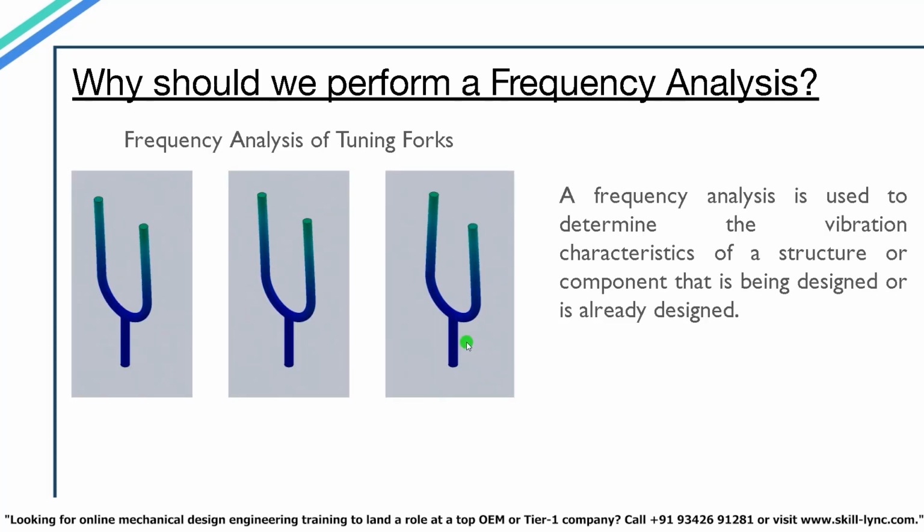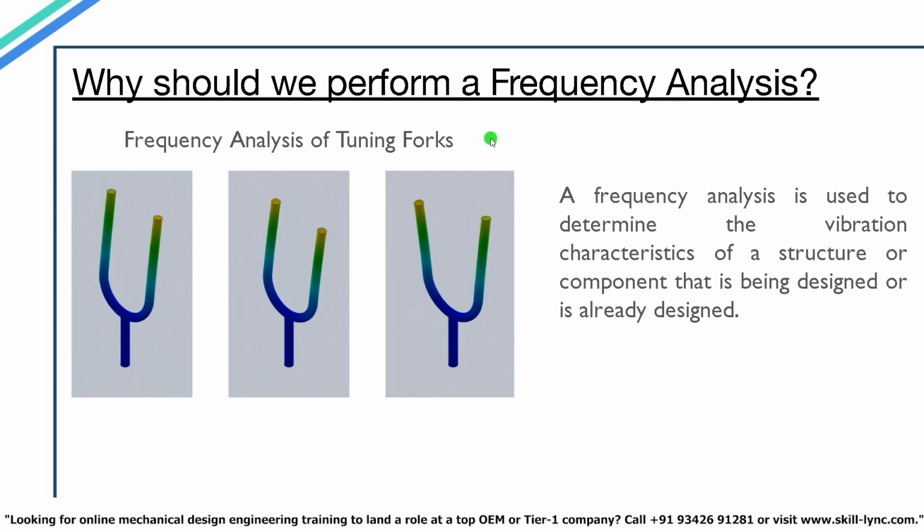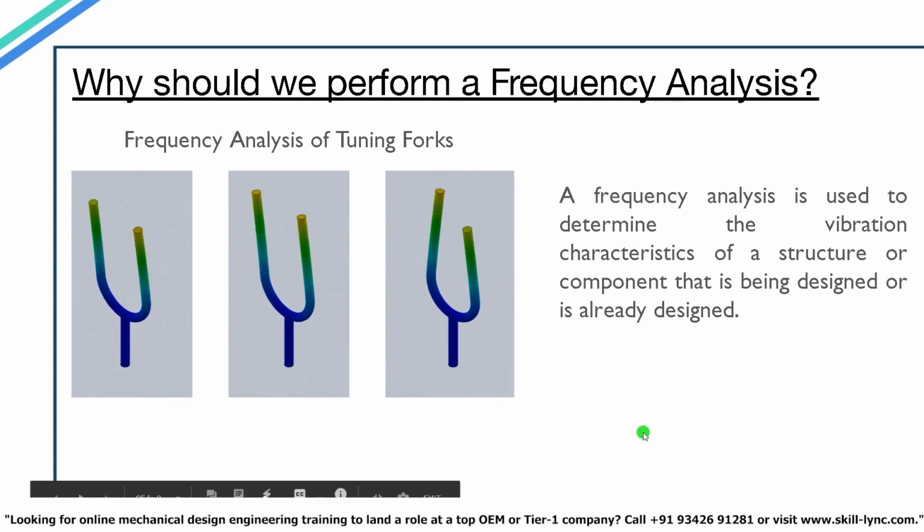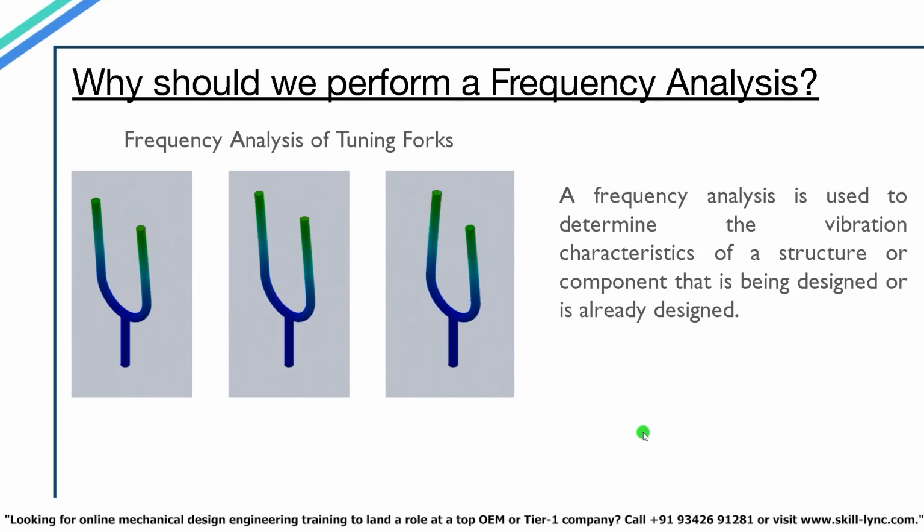The first question that we will be asking ourselves is, why should we perform a frequency analysis? A frequency analysis is used to determine the vibration characteristics of a structure or component that is being designed or is already designed. So why is it important for us to know how an object vibrates or at what frequency it vibrates? To understand this, we need to have knowledge of two topics. The first one is natural frequency and the second one is resonance.